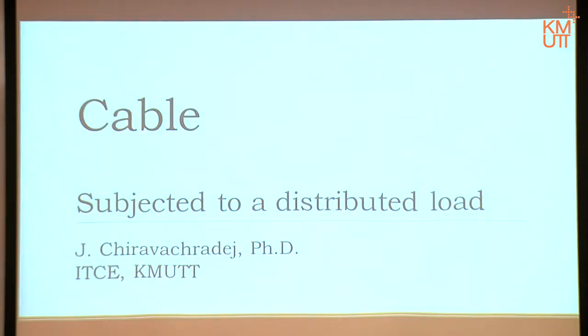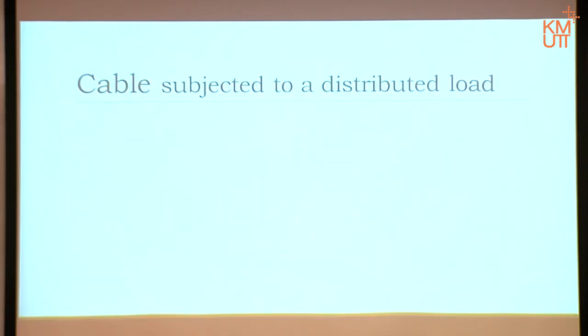Okay, but nevertheless, we carry on from yesterday. Yesterday we studied cables accepting point loads or concentrated loads. Today we look at cables that take a distributed load. Since the introduction was done yesterday already, I'm just going through it quickly. We will talk about the application first, again quickly, and then we start to formulate how we gain equations to calculate the forces inside the cable itself, in this case, of course, tension.